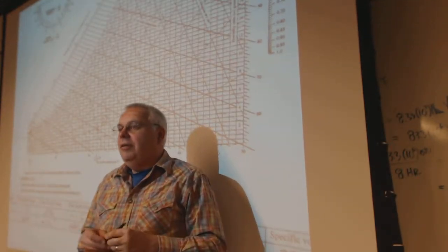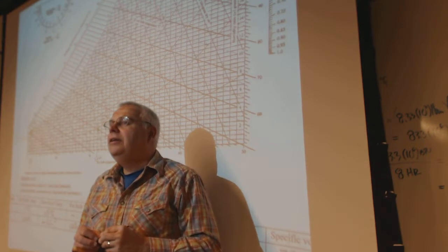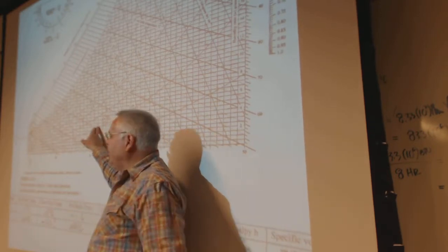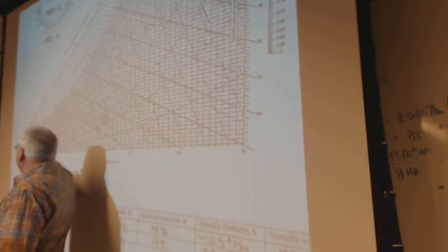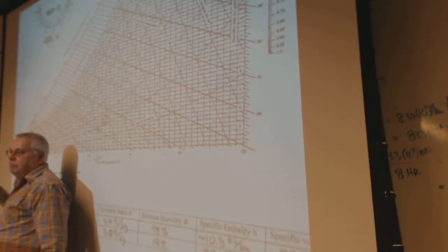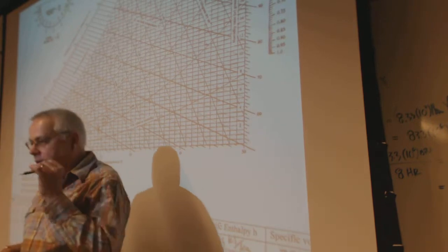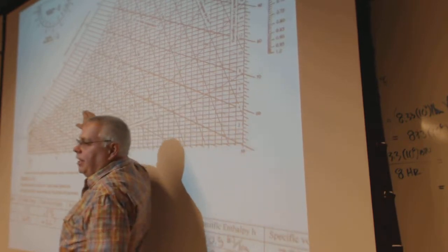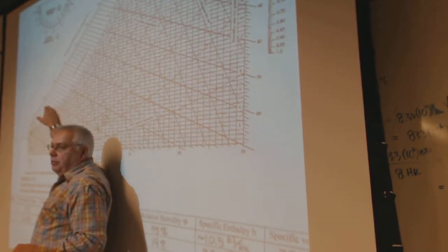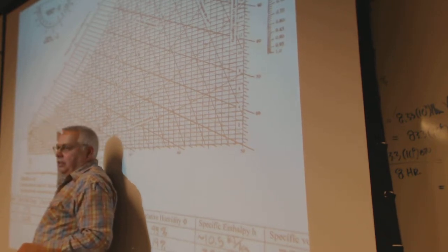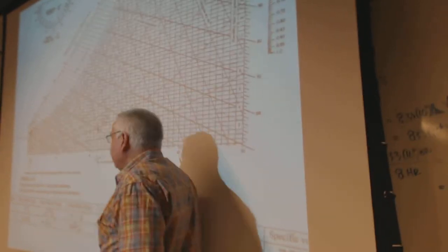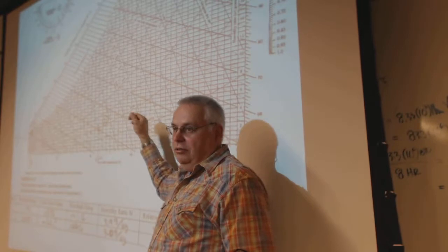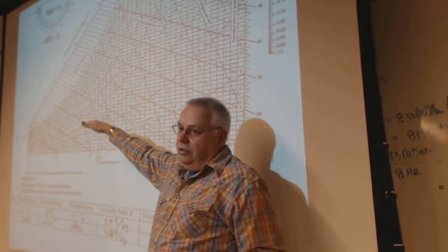Jason? So our wet bulb, dew point, you just go up and point straight left. Dew point, yeah, you're taking the amount of moisture in the air and driving it to a temperature at which that pressure is its saturation. So wherever it meets the saturation curve is your dew point? Yes. And then your wet bulb is the diagonal lines? Wet bulb takes the same amount of enthalpy and evaporates water, and when it evaporates, it drives the temperature down along that diagonal. So wet bulb follows the diagonal. Dew point follows the horizontal.